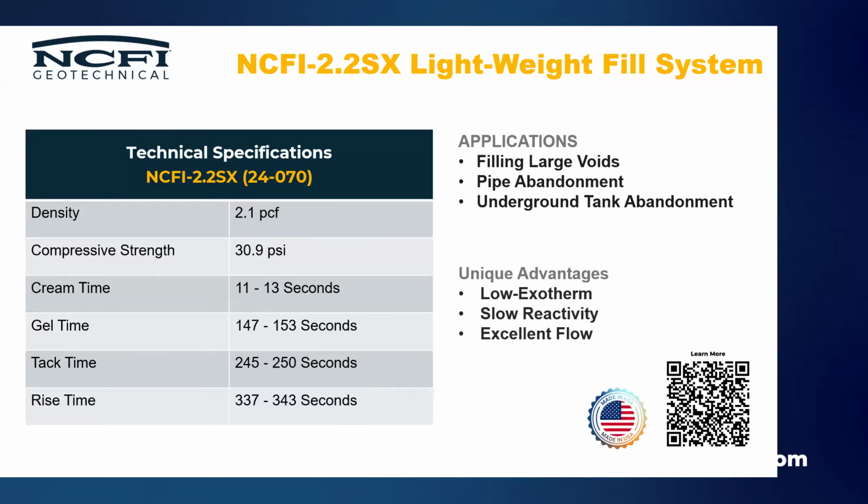So we're going to be addressing, you're going to see a couple of videos on some of these systems, but we're going to start with the lightweight fill stuff. These lightweight fill systems are great. They're all going to be in that 2.2 pound per cubic foot zone. Some may come in a little bit lighter at 2 pounds. If it packs in some, you might get it up to about 2.5 pounds, but extremely lightweight compared to your alternatives out there. Great for filling large voids.